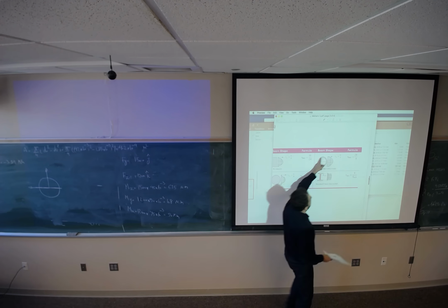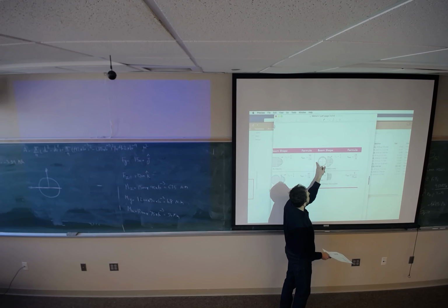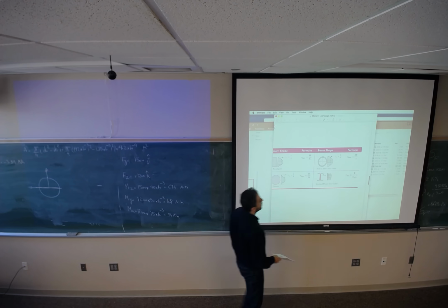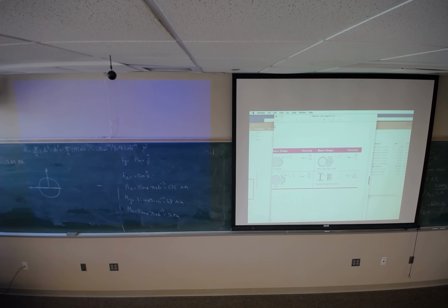For the cross section that I have, as you see, the maximum shear stress occurs at the middle point, which is point P, located on that, and point A is gonna see the shear stress equals to 0. So I'm done with these two.